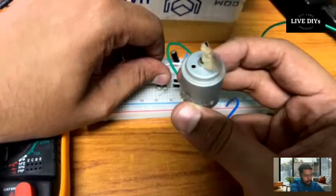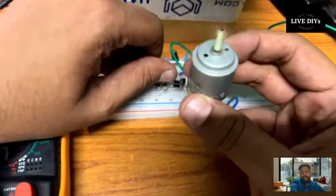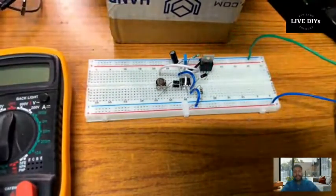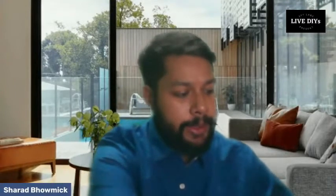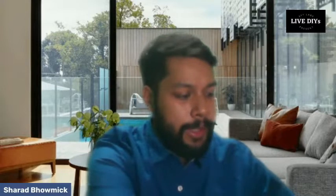So we are using basically PWM. Actually, we can control the speed of the motor even by using a resistor, but that is not the efficient way, because in that case the efficiency goes down since a lot of energy is wasted in heat. So what I'll do is remove all the components and show you all the important components in the project, and we'll design it once again.